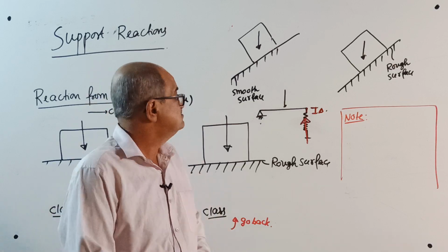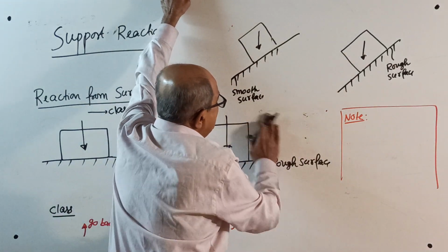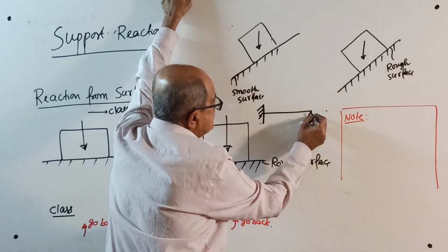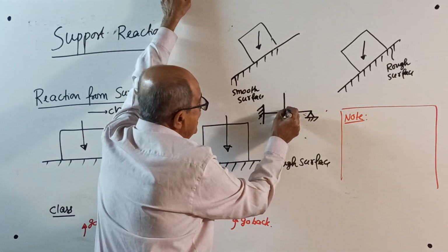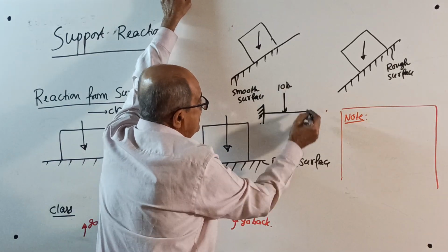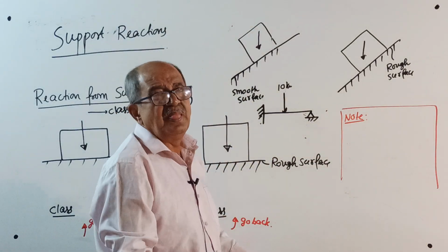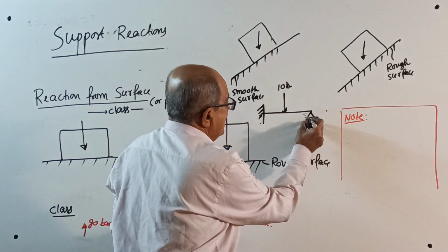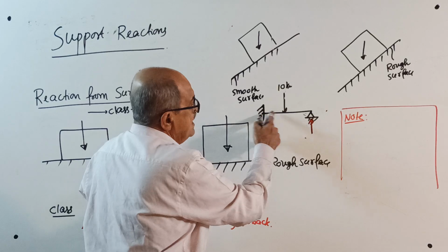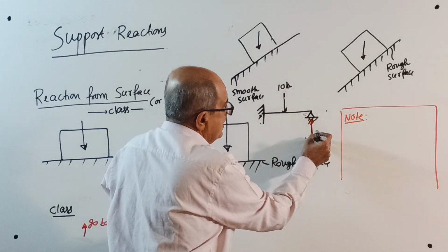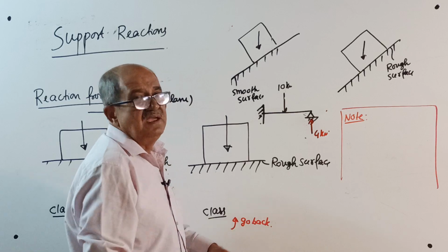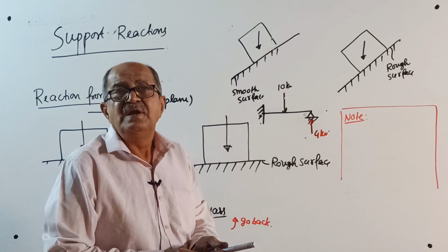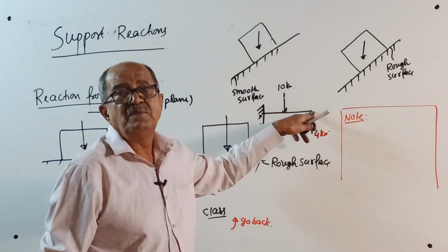It all comes later. But remember, suppose there is a beam, one side fixed, and the other side you put a rigid support. You apply a load here, 10 kilonewton. See, this support is not moving. It will prevent the vertical displacement. So it will give a reaction of, say, for example, 4 kilonewton. Just imagine, 4 kilonewton is the reaction if there is no displacement here, meaning rigid, displacement prevented.